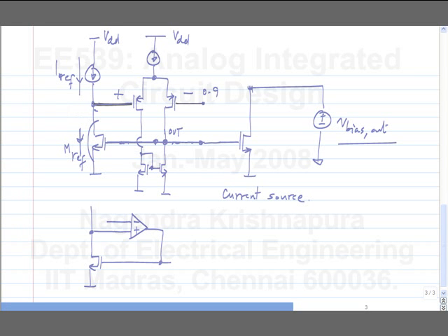This is not just for an op-amp. Anywhere you want a very accurate mirroring, you will use this. You look at the voltage to which the current source is driving its current, and you make sure that on the reference side it is driving the same, the VDS is the same. So is the circuit complete now? Or do we need to add something? Will it work as we expect it to work?